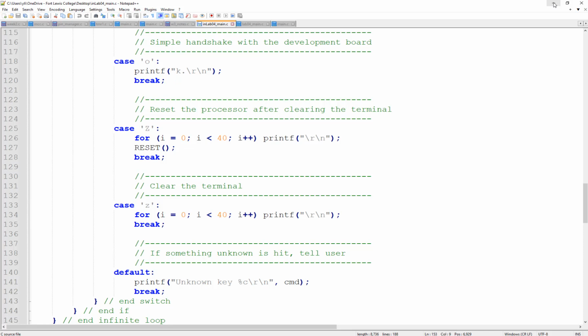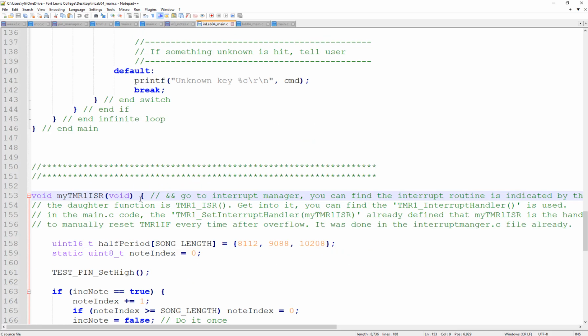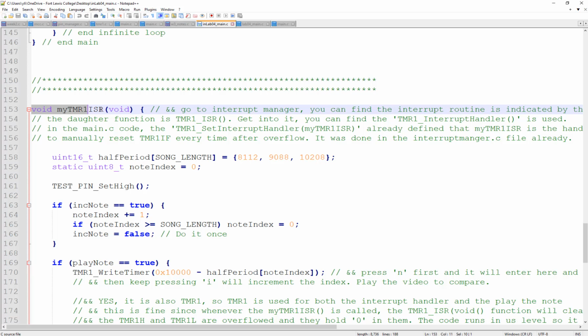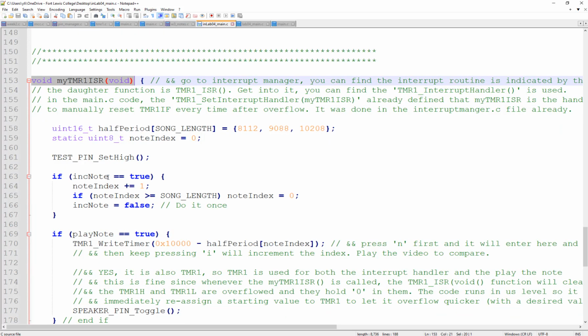Now let's come back here and take a look at it. What's happening? Concept-wise, it's really simple, right? This function, no matter where the program is at, where the program pointer is pointing, taking every single instruction through the program memory and putting it to the CPU to do the calculations, that's how the computer works. But no matter where the pointer is at, when the timer is up, it's going to jump into here and do the job. Okay?